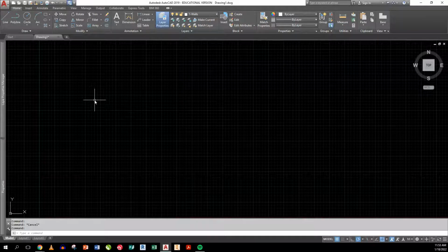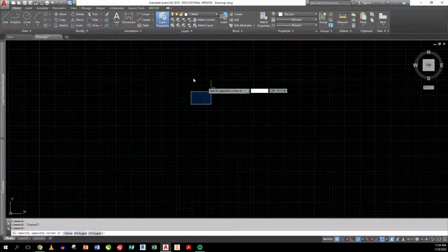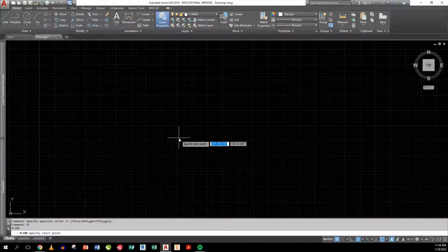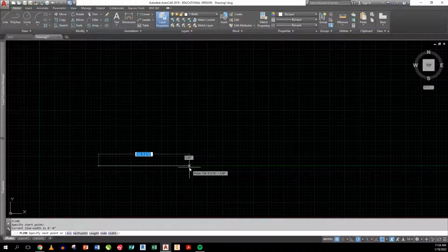Okay. At this point, I'm going to do a polyline. Now, I always start my houses with polylines for a couple of reasons. So if I just start anywhere, it doesn't actually matter where. Polyline, I'm going to pick a spot like, say, right here, drag it straight out. Now, the reason I do polylines is because we have to establish wall thickness. When we draw it on paper and are sketching, quite often we just use thick lines, like draw a couple lines next to each other, make them thick. In a CAD system, we need to be much more precise.